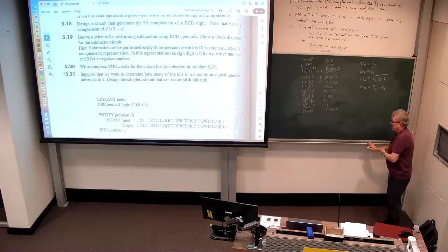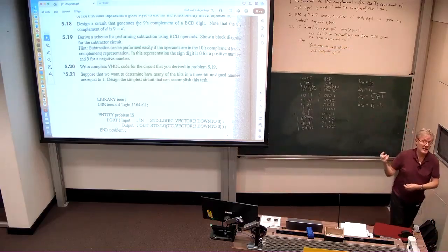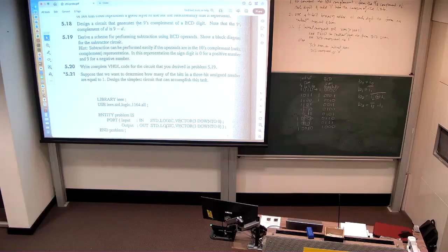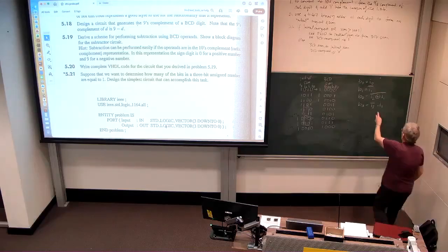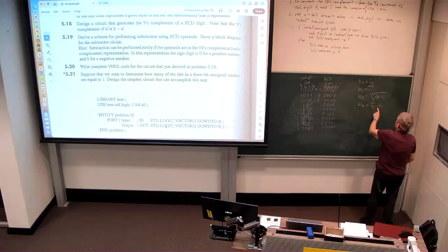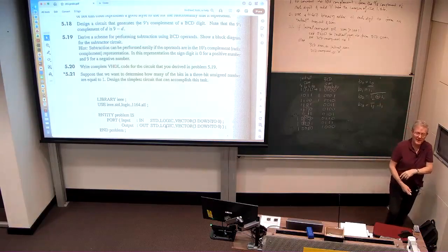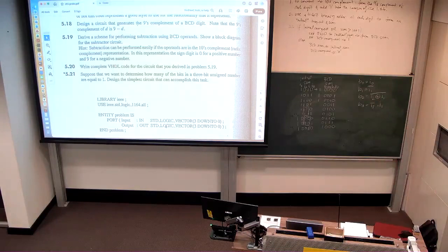So, clearly that's better than having another adder, because you've got 4 equations and there's literally only one inverter, two inverters, one AND gate, and a slightly more complex gate, the exclusive NOR gate, required altogether instead of 4 full adders, because you're only adding 6, it's a very specific number. That's always going to be a lot cheaper than having a general purpose solution like a full adder or a full 4-bit adder to do your addition for you.